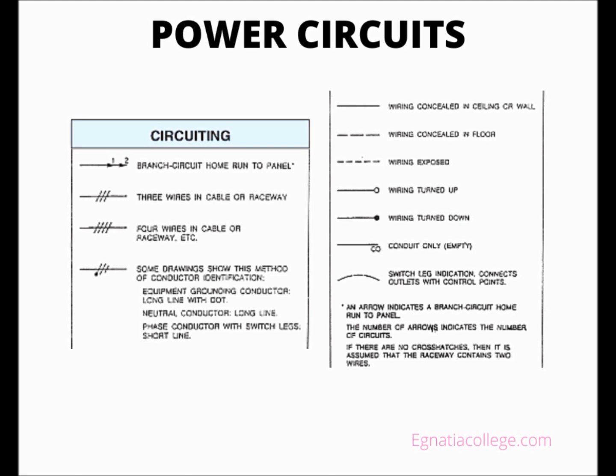Some equipment, such as television, fire alarm, clock, PA, and sound, might not be connected with wiring lines on the plan. This indicates that wiring for that equipment is not part of the general circuit wiring and is probably not to be fed through the same panels as the rest of the electrical equipment. For example, on the school addition, the PA system and the clocks are fed from the sound system console and do not involve the general circuit wiring.